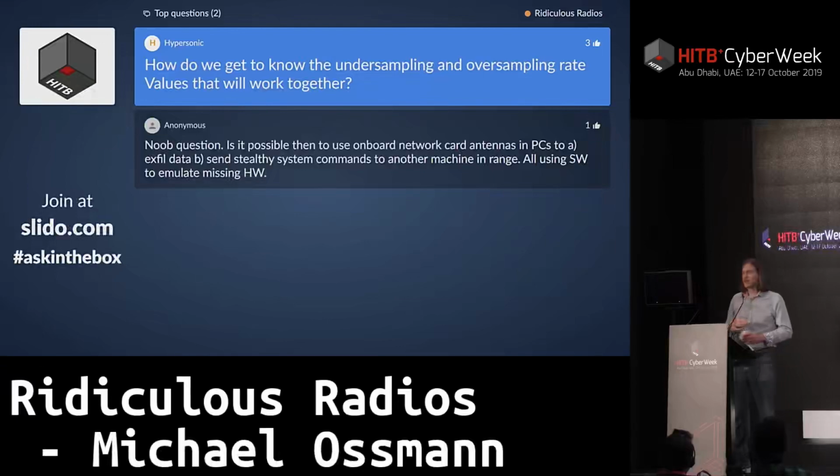We were sampling that ADC pin or that GPIO pin. And generally speaking, you can get away with undersampling, but only a few times your sample rate. So we were about half the sample rate. Our sample rate was about half the frequency of our target, and that worked okay.